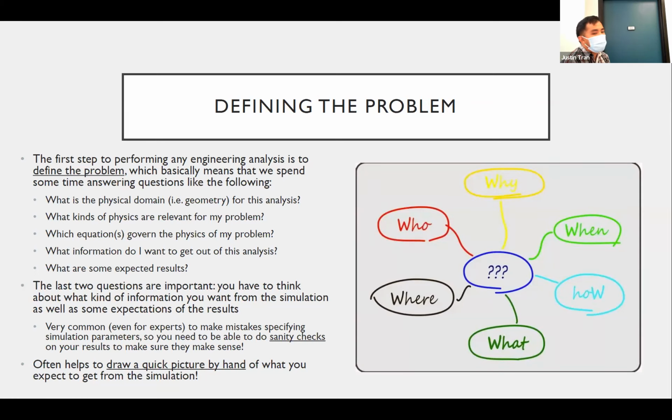And so you can look at those results and immediately say, this is not correct, because the pressure inside a person, there's no way for it to be infinity. And so it's always good, when you run a simulation, to look at the results and to perform a sanity check, right? You look at the results and think, does this make sense? Does the result I'm getting make sense, or did I mess something up with the setup?